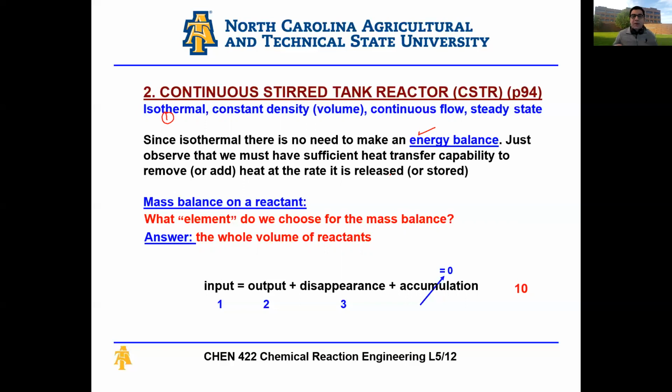In most cases, reactors are kept running under isothermal conditions, especially in industrial reactors, where you want to keep good control of your species and your thermodynamics. If you have hazardous chemicals, toxic chemicals, high pressures, whatever it is, you want to keep them all under controlled conditions, and this means operating them isothermally. So this is actually a valid assumption, and these equations are quite valid for many applications.